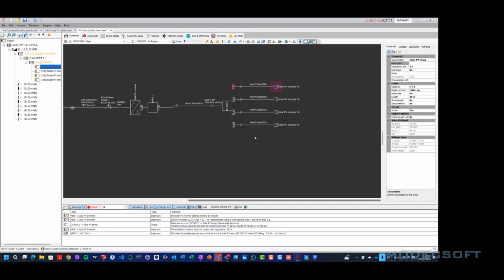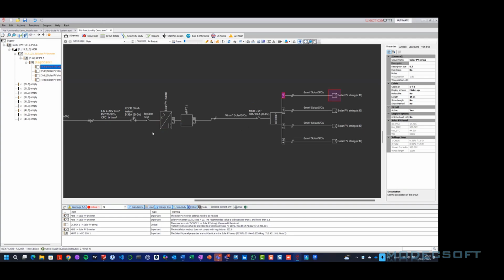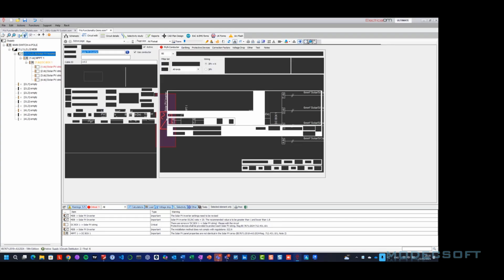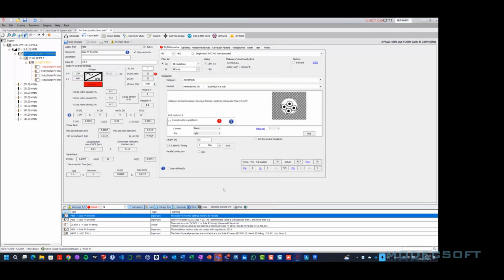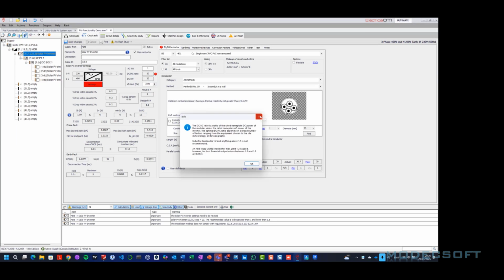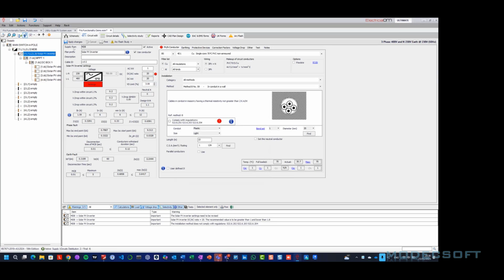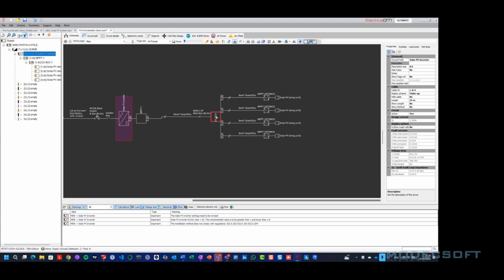Another way to deal with these warnings is to add power optimizers, of course. So I have to go back again to my solar PV inverter, enable the optimizers option, apply the changes. I'm not going to bother with the DC to AC ratio here. We know that we significantly exceed the capabilities of our inverter. Just for the sake of this example, we are going to omit that.